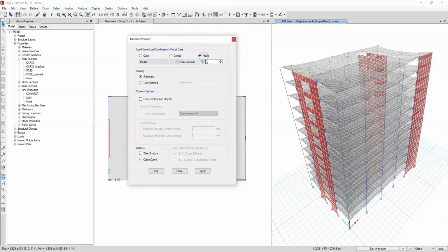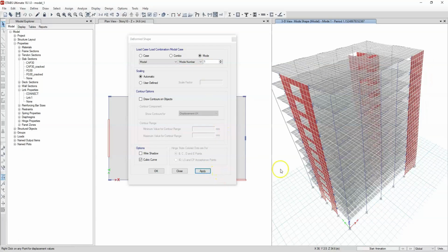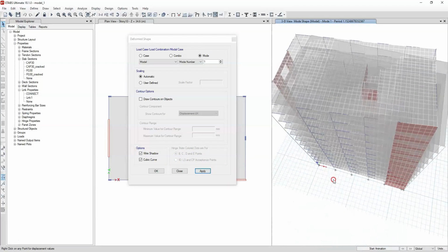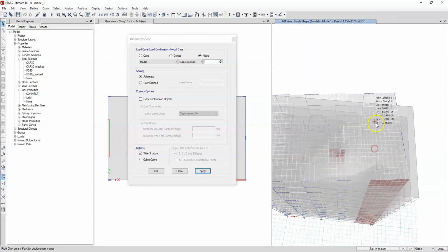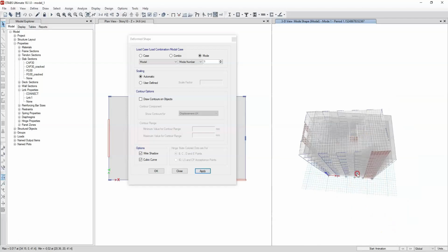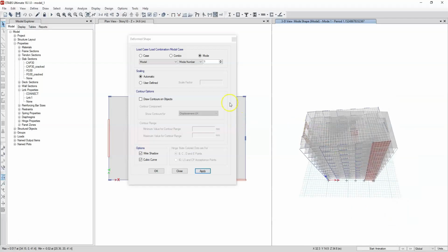But the modal analysis we performed was based on an initial structure with nominal stiffness, without any type of reductions. For this initial analysis, that is quite acceptable. Let's look at the vibration modes. Right now, we are looking at the first mode in plan. Using some perspective to perceive that this mode is clearly not a purely translational vibration mode. That is, it is translational, but it has some rotation or torsion.